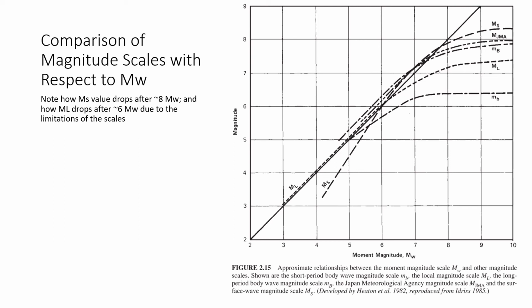The main limitation of your local magnitude scale is that it depends on a Wood-Anderson seismograph. Another limitation is that it doesn't account for the size of the fault plane that has displaced. So remember that when you are dealing with large earthquakes, the displacement starts to plateau as earthquakes become increasingly large.